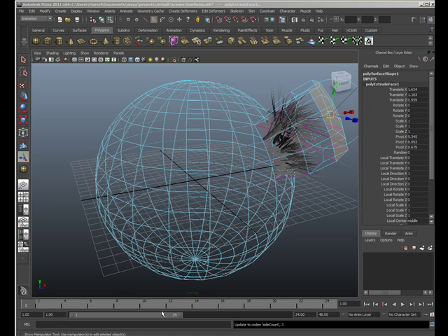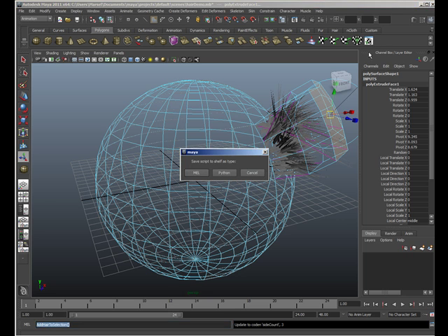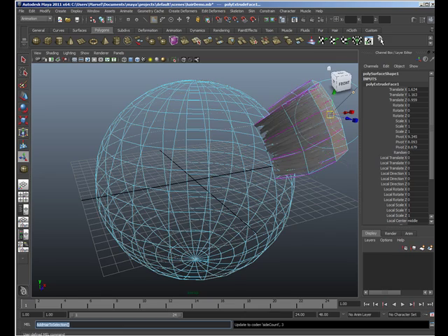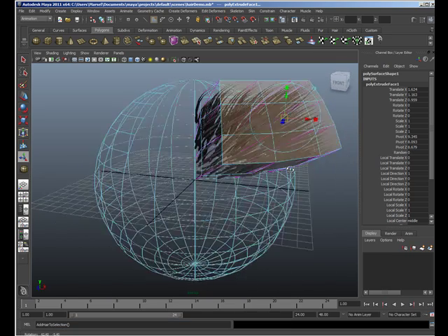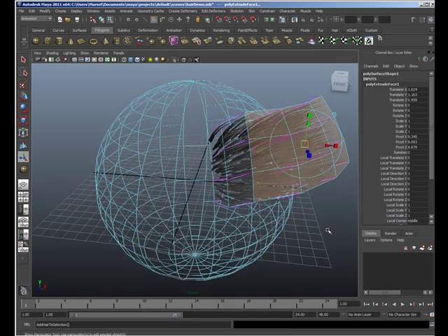That is because we need to use our magic function, Add Hair to Selection, to specify the new faces that should reflect our hair tips. To save me some time from going to the script window over and over again, I will drag and drop the function onto Maya's main toolbar, thus generating a button for it. When I press the button, the function gets executed again and our hair is updated accordingly.